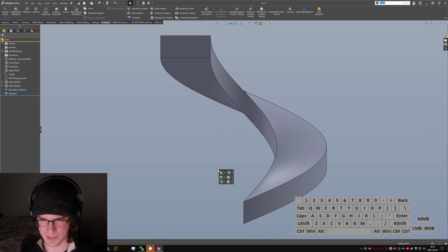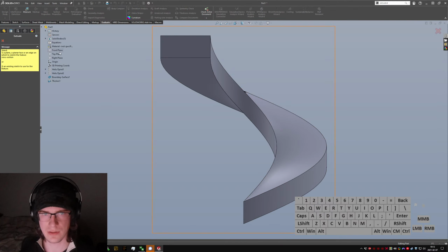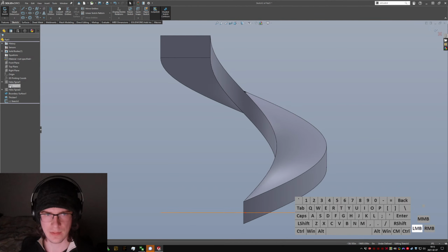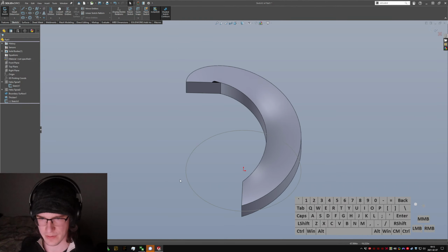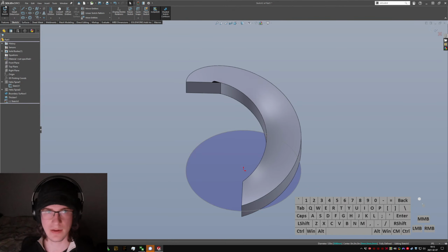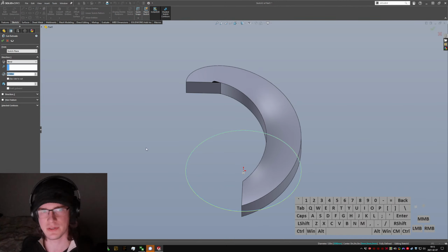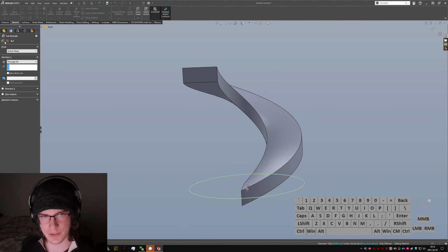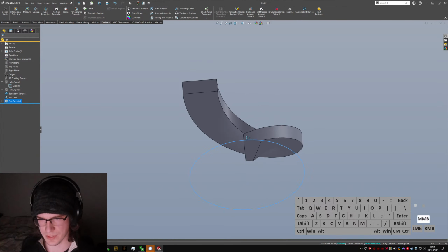We need to cut the first step. We also need to cut below it. We'll do the separate lower cut first. So extruded cut, top plane, pick the first sketch from our outer spiral. We're just going to convert that, exit sketch. So now we've grabbed the geometry from our first feature and we're using that to reference later. Then we say through all, and it should just cut that shape off of the floor.